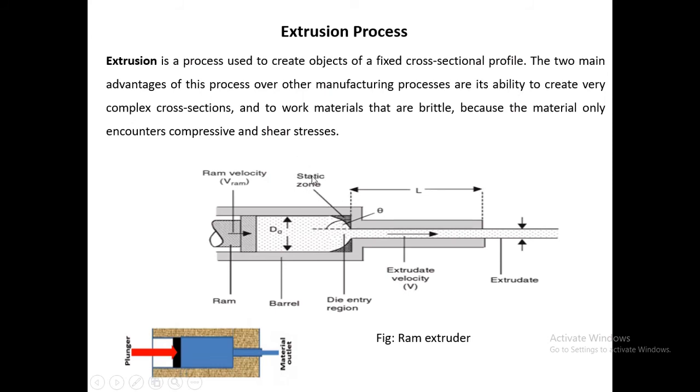And in the second stage, the ceramic mix powder is added into a chamber where it is sealed and air removed to create a vacuum. And the third stage is where, using a ram or plunger force, the plastic mix of ceramic powder is forced through a constricting die to produce an elongated shape that has a constant cross section.